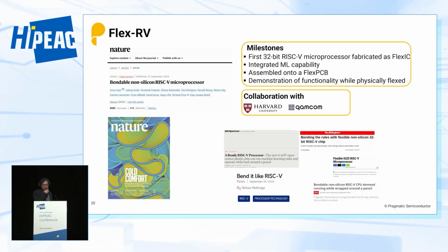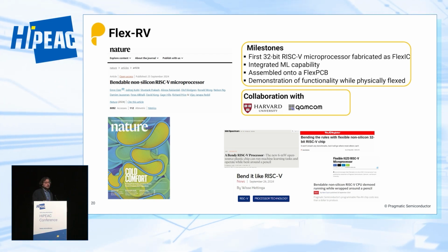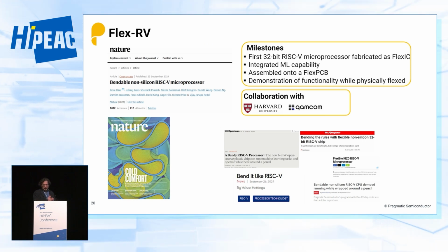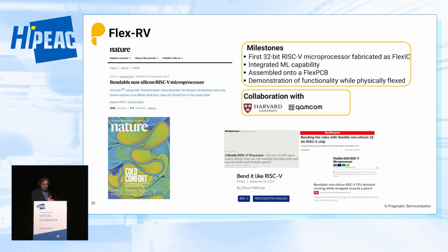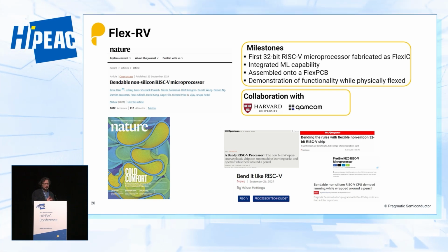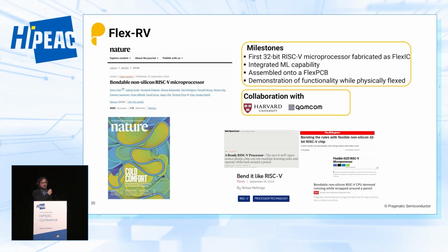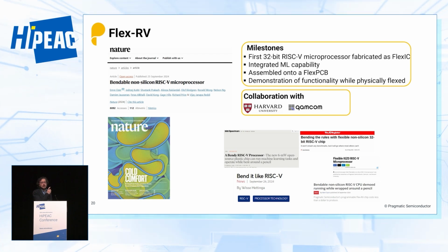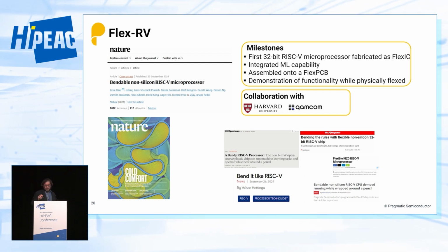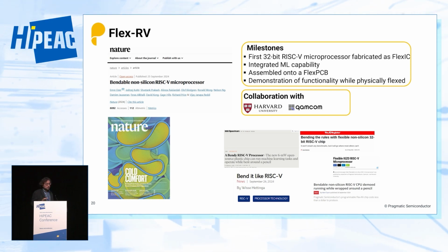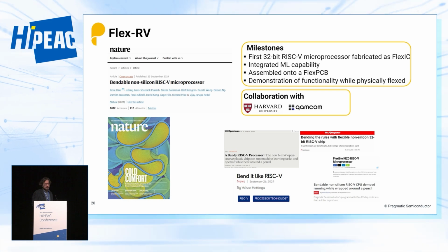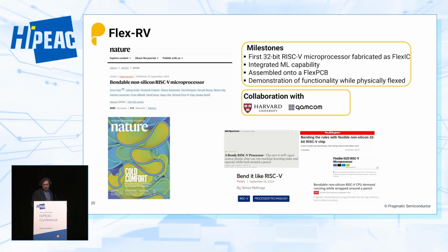So, to summarize, this is the first non-silicon RISC-V processor. I guess we can claim that. It's also an SoC, and the difference from the plastic arm was that we also integrated a very basic small ML hardware accelerator tightly coupled to the CPU. And we assembled this to a flexible PCB. I will show the results, and there's a video as well.